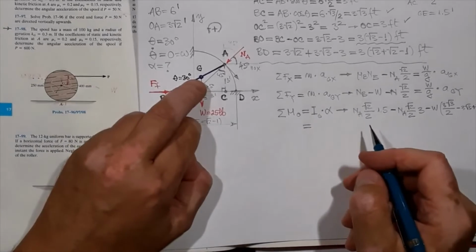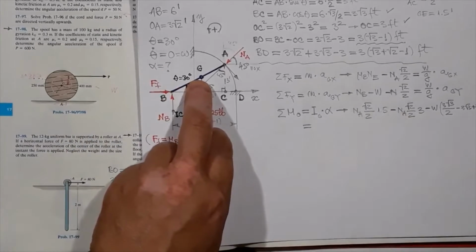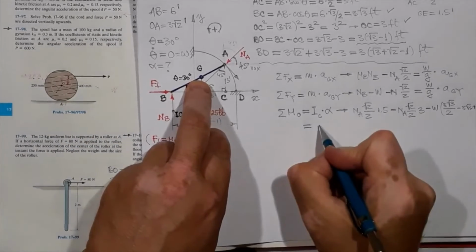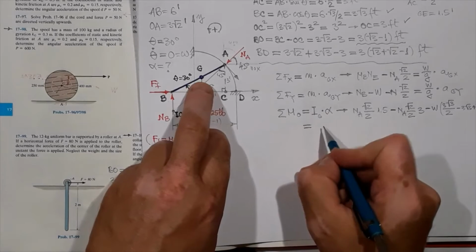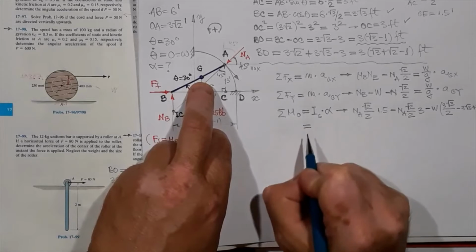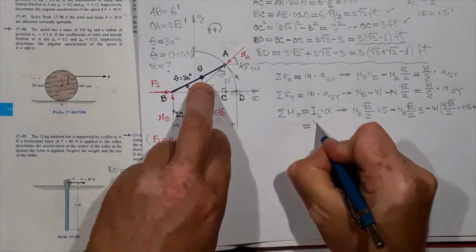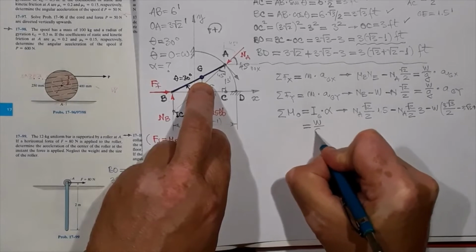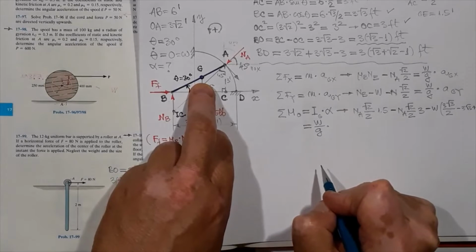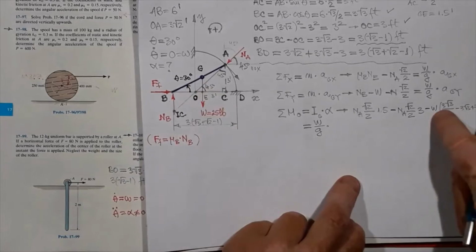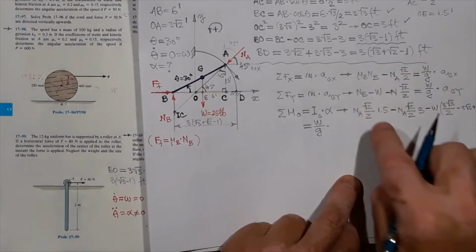And this is equal to, we've been here before, the mass moment of inertia about the centroid of a slender rod is going to be 1 over 12 mass times length squared, so that's going to be weight of the bar divided by g times length, well, I have weight, I use weight, but this is known.